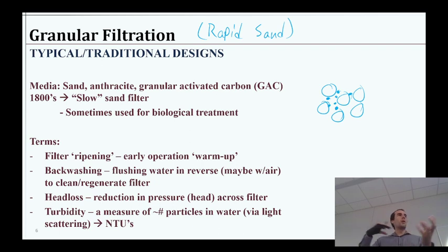But as soon as you get a few particles settled, and maybe the granules themselves shift and settle a little bit after a few minutes of operation, they start performing a lot better in terms of separating particles. So early on, right after we start with a very clean granular media, we don't get very good separation.